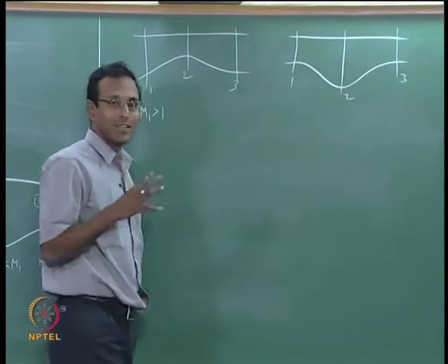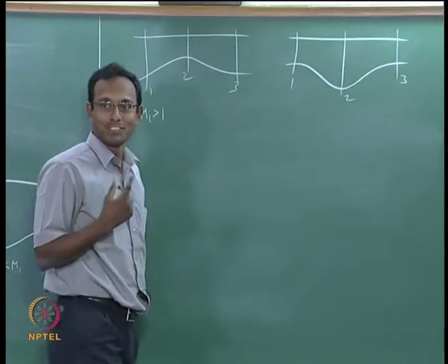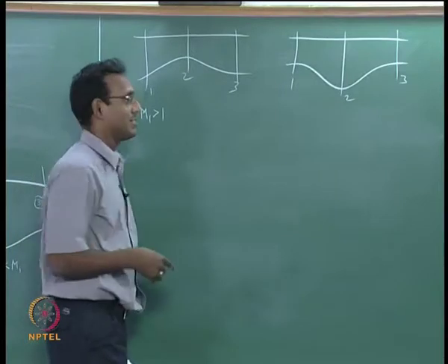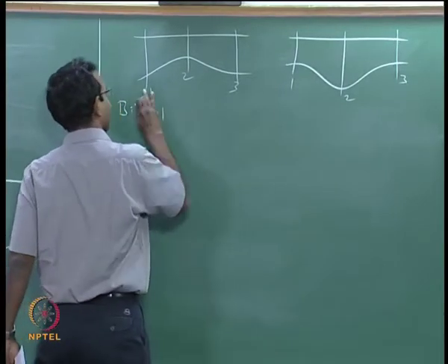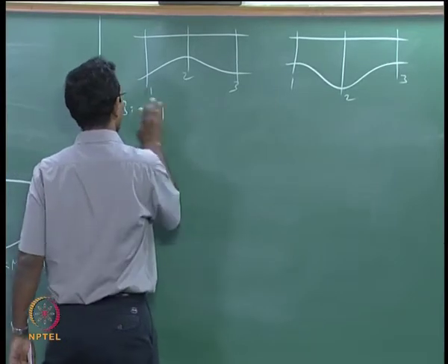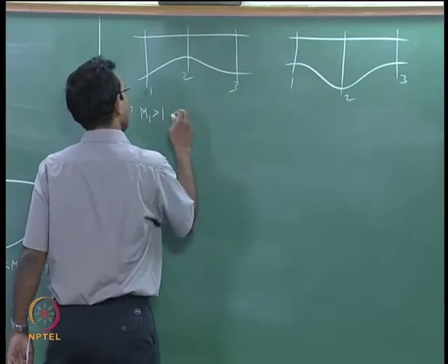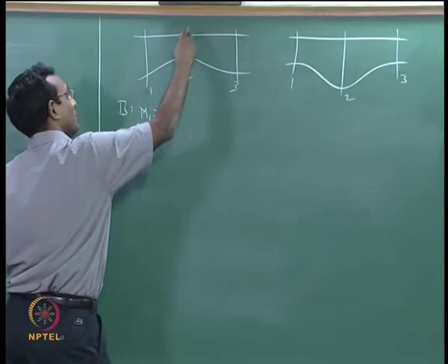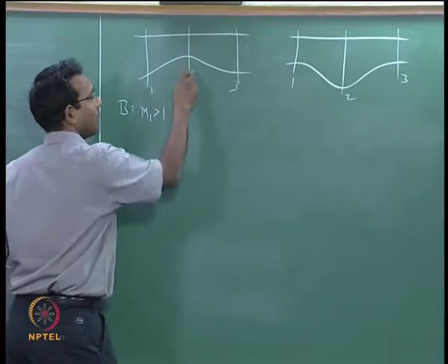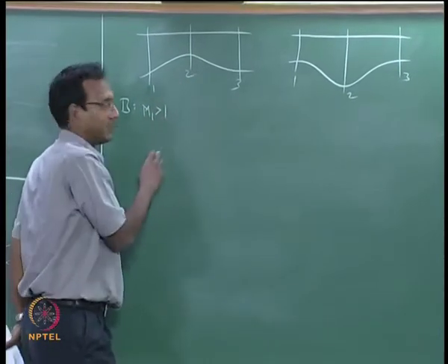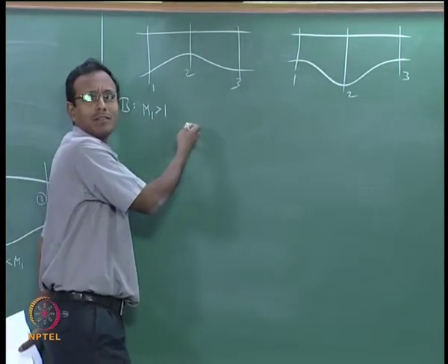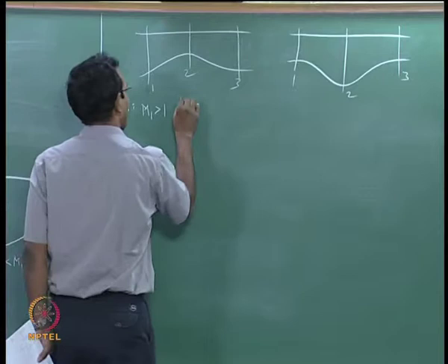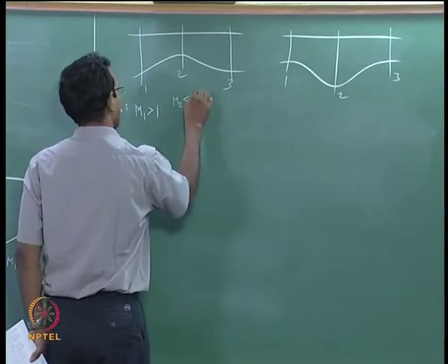But this may get confusing after some time. If you do not remember which is towards, which is away, you will get confused. Instead remember the other statement also. I like this statement anyways, you have to get used to something in your compressible flows. It is supersonic, it is going to go towards M equal to 1, which means 1.5 will go towards 1, maybe it will become 1.1, I do not know. All I can tell is M2 less than M1.